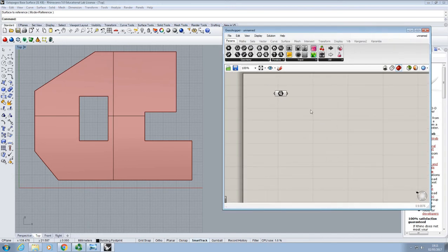So what we'll do is we'll set up our grid. And to control our grid, we're going to want to set up 4 basic parameters. We're going to want to have the spacing of our grid in the x direction, the spacing of our column grid in the y direction, and then also a position of that grid in 2D space. So a kind of a start point to that grid relative to the origin there, so that we can move that whole grid around and fit it within this region. So we're going to have 4 basic parameters for that.